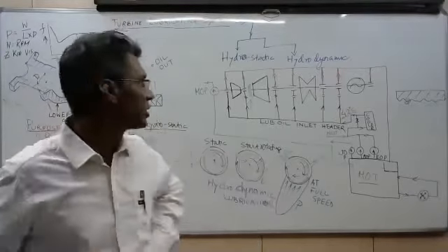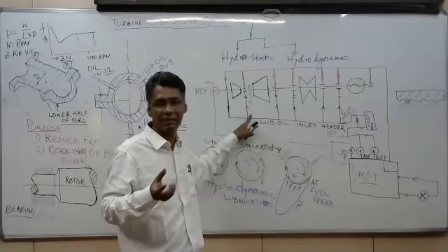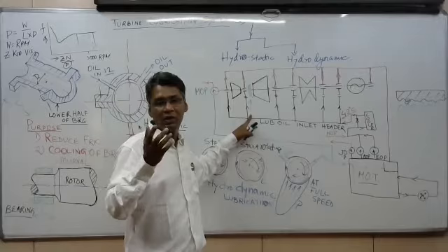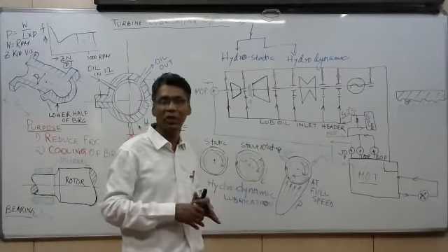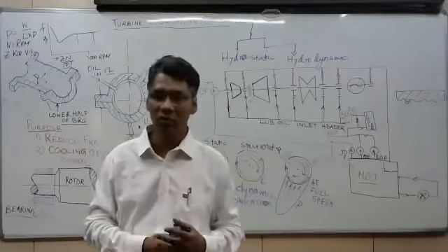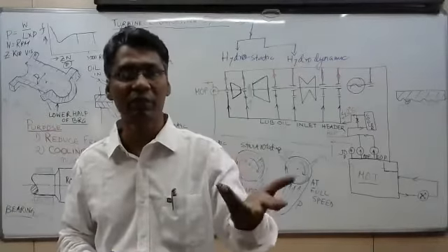Suppose 1.2 kg oil pressure is given, and suddenly pressure goes down to 0.6 kg. That means the amount of oil being provided is not the same. So that's why you have to maintain some oil pressure over here to maintain the quantity of oil across the filter. But hydrodynamic lubrication will take place automatically.